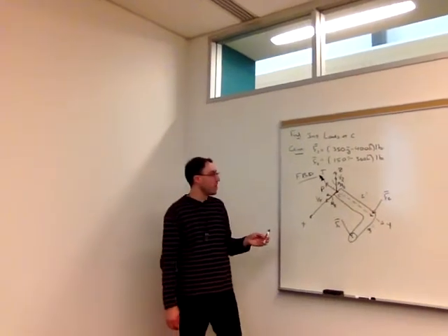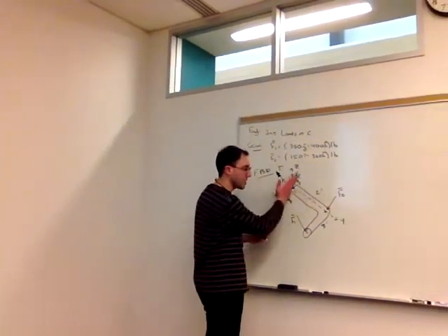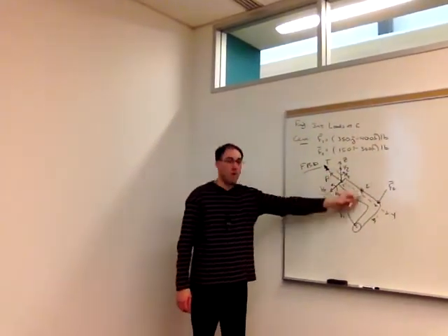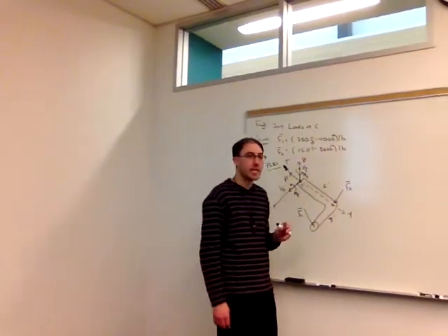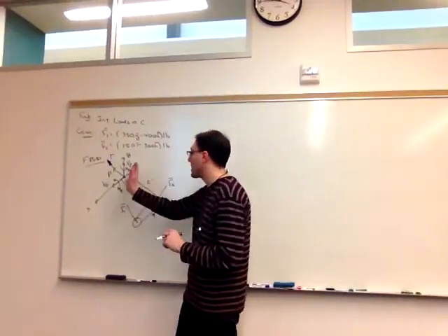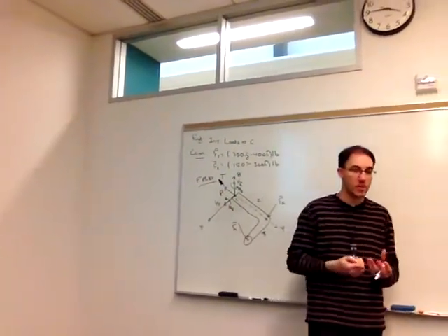So I've introduced 6 unknowns here, P, T, Mx, Mz, Vx, and Vz, and because I took everything to the right of my cut, in this particular example, there are no reactions, so I did not need the external free body diagram, although if you want to check this and take everything to the other side and find these values, you're going to get the same answers.